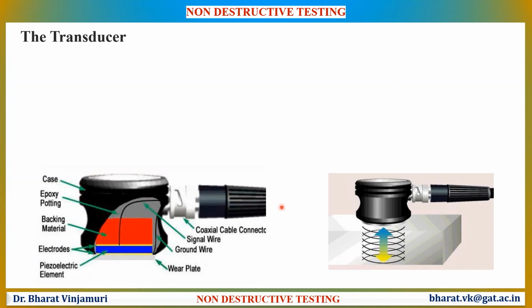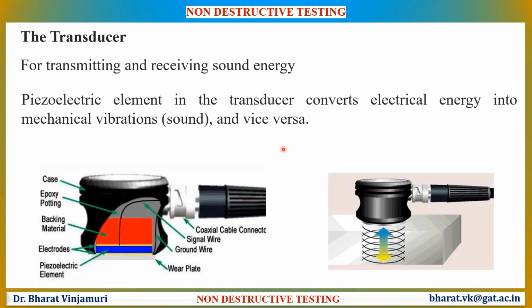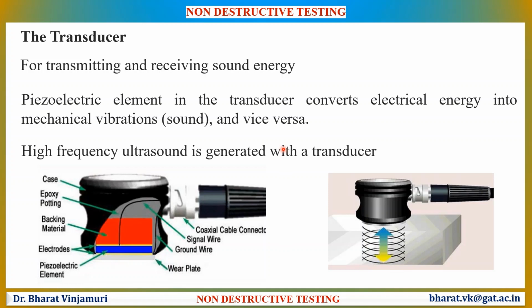The most important component of ultrasonic testing is the transducer. An ultrasound transducer, also called a probe, is a device that produces sound waves. The transducer also receives the echoes and sends them to the computer that uses them to create an image called a sonogram. Moreover, the essential element of an ultrasound transducer is the piezoelectric crystal. This piezoelectric crystal converts the electrical energy into mechanical vibrations.